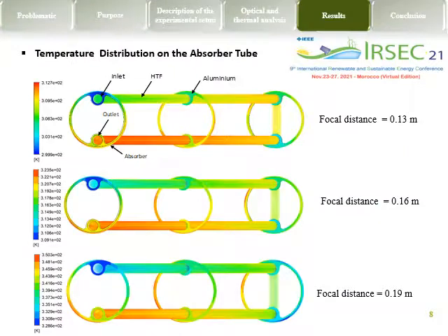As a result of this study, we can see clearly the temperature distribution on the absorber tube for all distances. The maximum temperature over the circumference of the absorber always appears around the part where the outlet liquid is located, for all distances. The maximum circumferential temperature on the absorber tube is about 315 Kelvin, reached for the distance of 0.90.